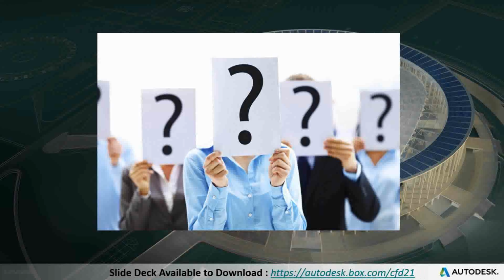So I always prefer, if I can get close enough with less tweaks, to use the less tweaks, because it's less that I can have an error that's going to show up in my design process. If you're using SST and all of a sudden you forgot to change one of your designs to SST, your K-epsilon results may skew you in the better direction, and it's actually error that you're choosing the wrong design. My extra take on it.